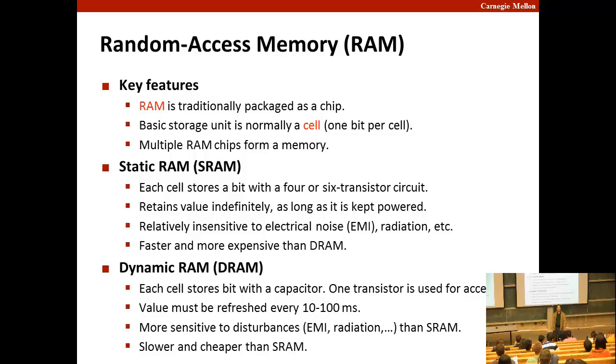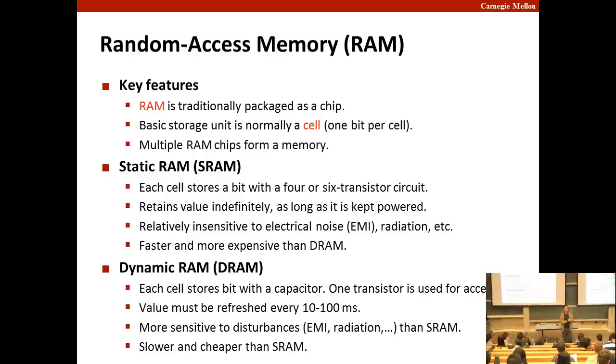But is that done by the memory controller outside of the row buffer, or a DRAM controller inside the row buffer, inside the DRAM cell? So the memory controller walks through all of DRAM linearly. If I have 64 megs of system memory, every 10 to 100 milliseconds, it's linearly walking through all of my memory. The entire system linearly. It can access different blocks simultaneously. It just can't access multiple parts of the same block at the same time.